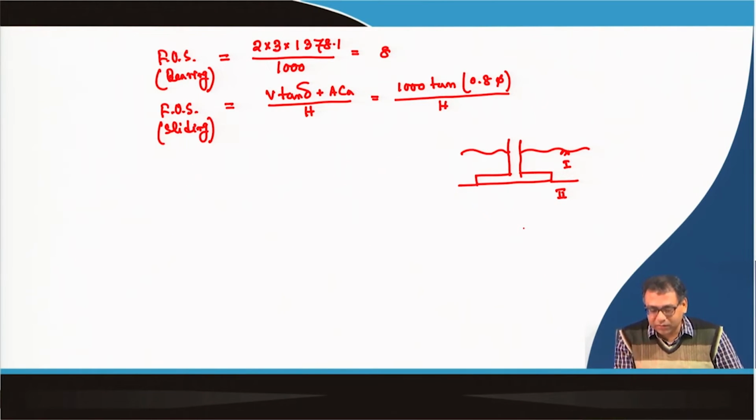So, now when you calculate that delta and the CA, do not take the soil properties of layer 1, you take the soil properties of layer 2, because it is the base interaction, where the foundation is resting. Okay. So, these are the properties that you have to consider for delta and CA. Similarly, for the second term, because there are three terms in the bearing capacity equation, gamma will be this gamma 1, and for the third term, gamma will be gamma 2, because that is below the base of the foundation.